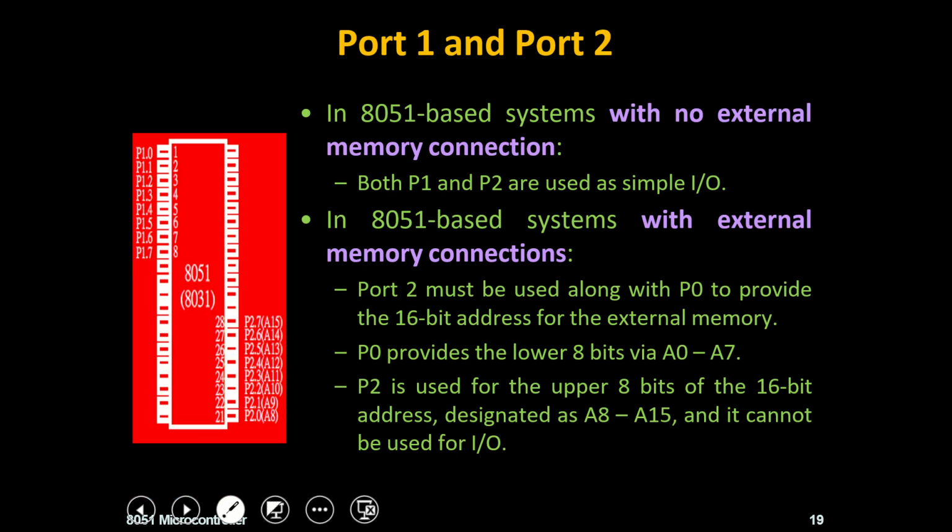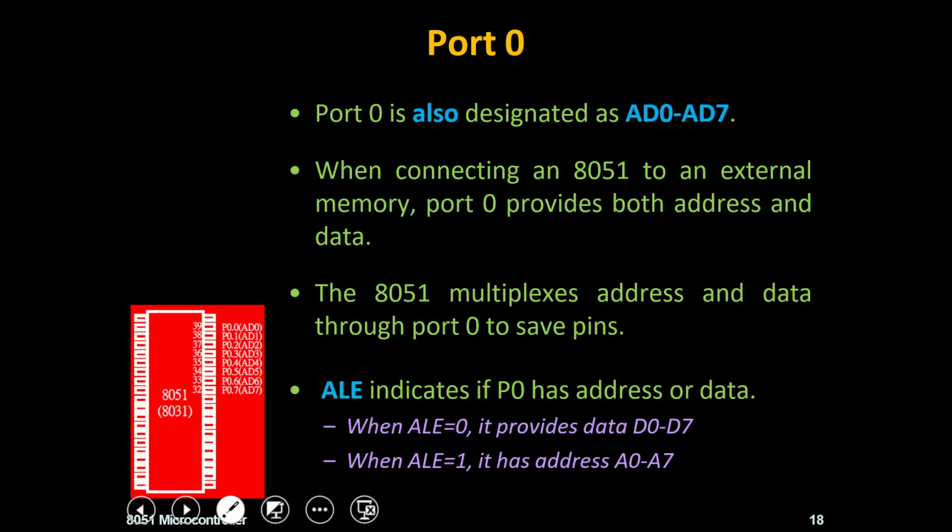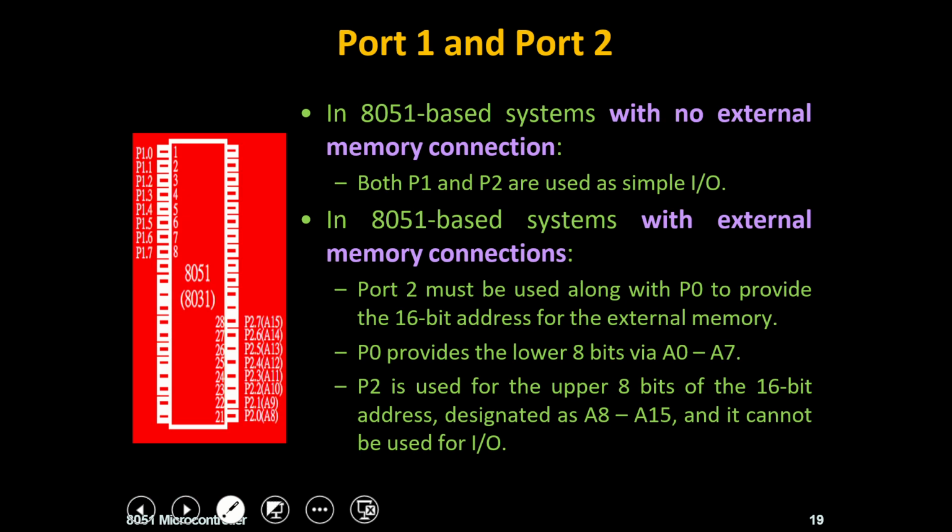Next one, port 1 and port 2. Compared to port 0, which is connected with the external memory, port 1 and port 2 have no connection with the external memory. So they have a connection with only input and output devices.